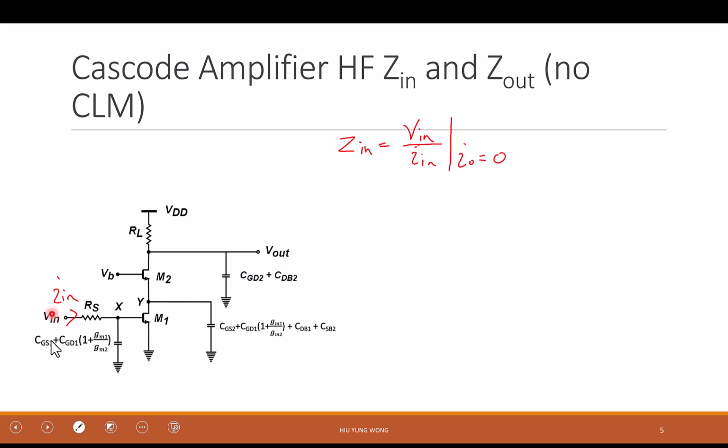So, what do you see when you go in? Yeah, the first thing I see is RS. Of course, I need to be very confident that seeing that just by inspection is correct, right? Because if the RS is actually connected to another transistor source or whatever, that won't be so easy. But now I clearly see that this is just like a resistor in front of me on the test bench, and then it's connected to a capacitor connected to ground.